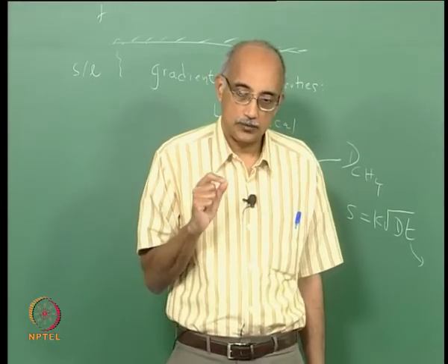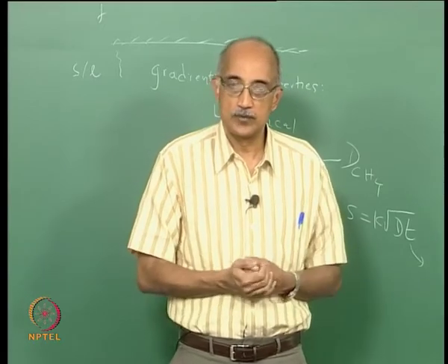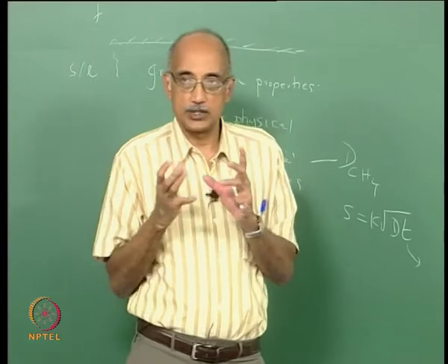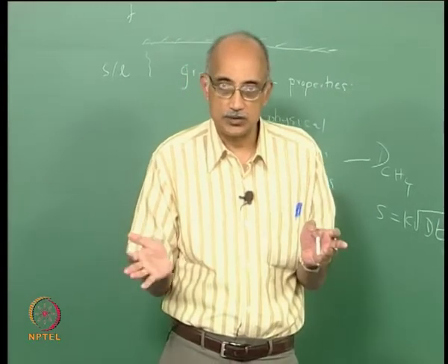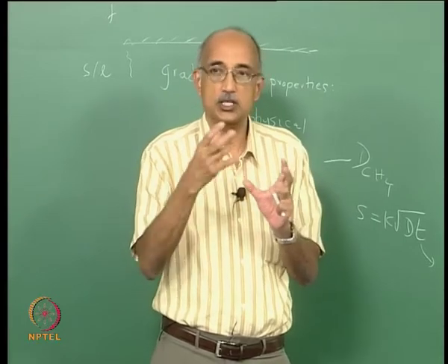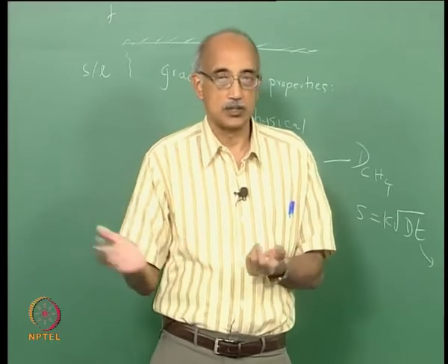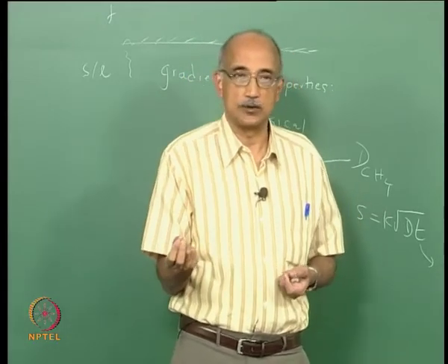But for example, let us say you are using silicon carbide as the abrasive material, you expect a certain structure of the silicon carbide, you expect to see a certain crystallinity, you expect to see a certain shape. It is all in the exterior of the particle, because abrasion again is a surface process, the core of the particle never gets involved, right.